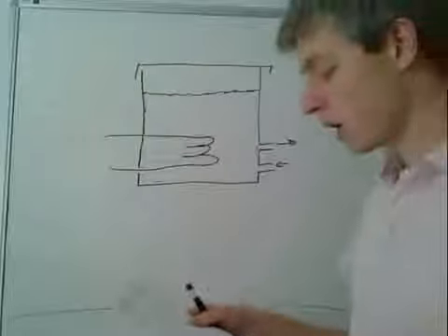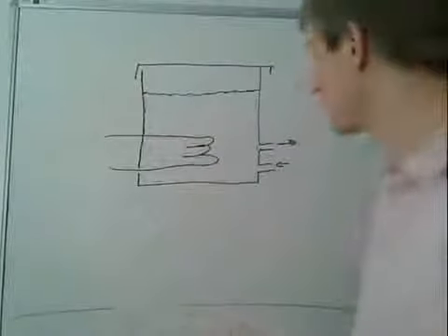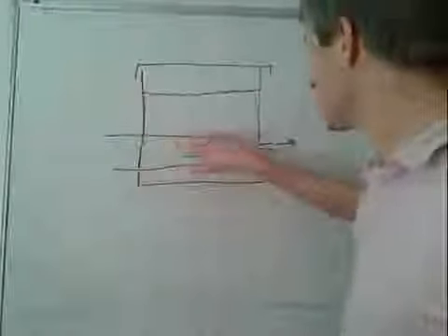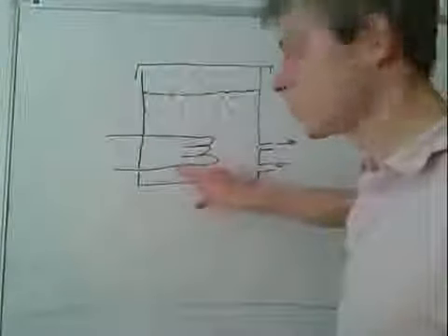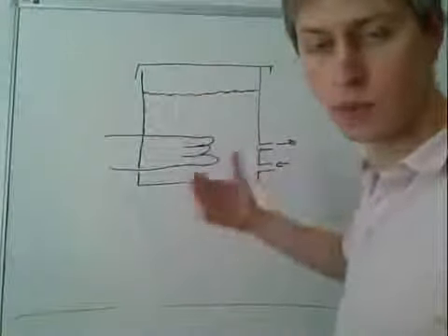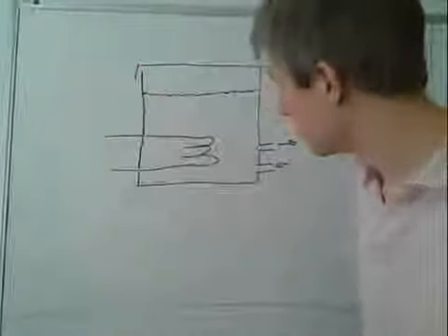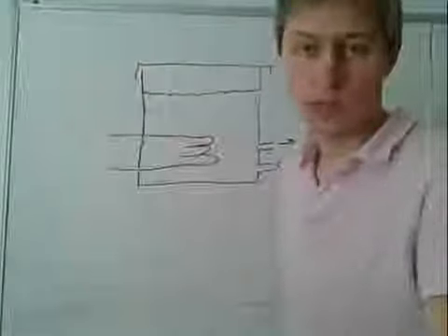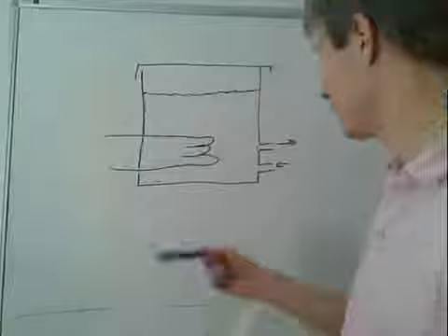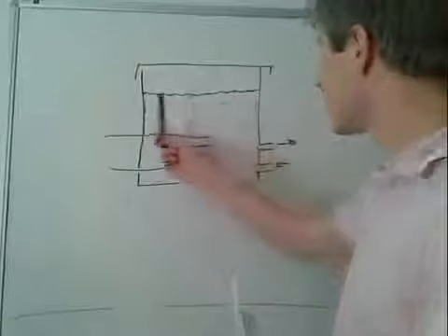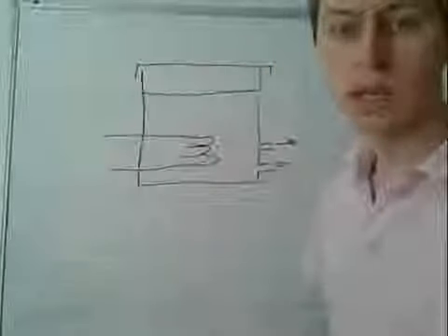Now, how is heat and work transferred in this system that we've now defined? Well, this heating element's receiving electrical power and being heated by electrical resistance, so it's going to be hotter than the water potentially. Heat will be conducted from the surface of the heating element into the water, and then can be transferred through the liquid by convection and further conduction. What else? We can have heat losses to the walls of the tank. Of course, we'd want to insulate the tank.